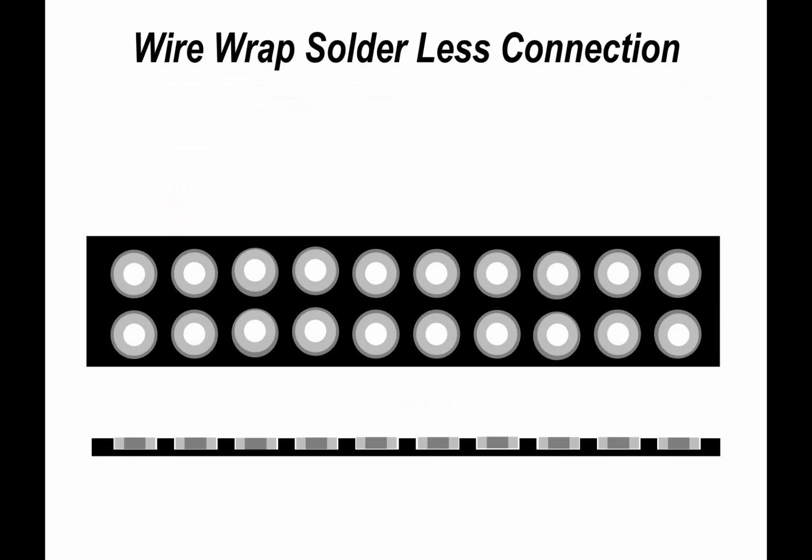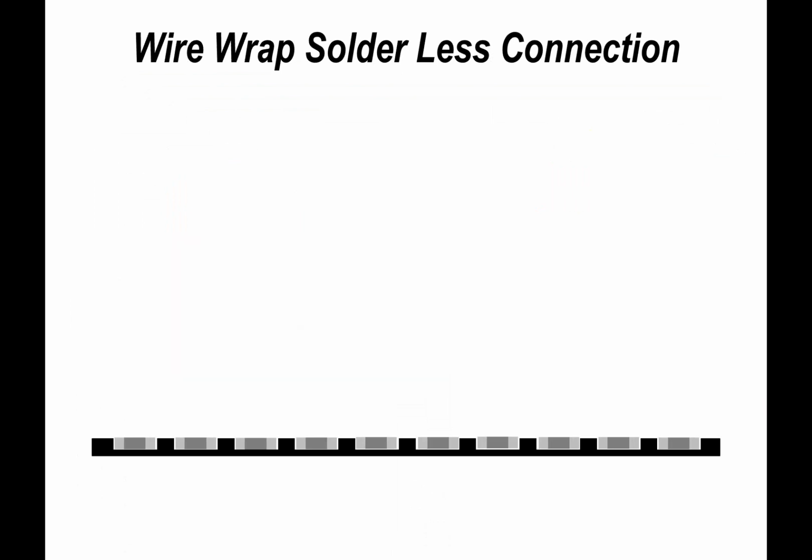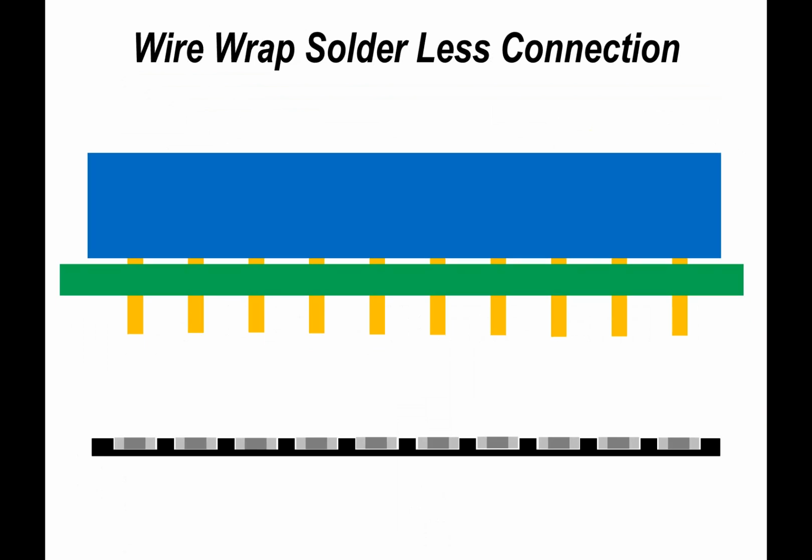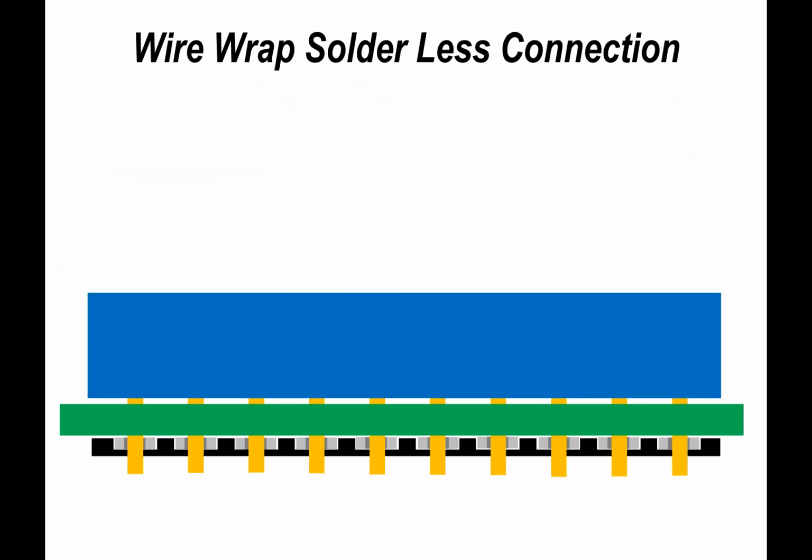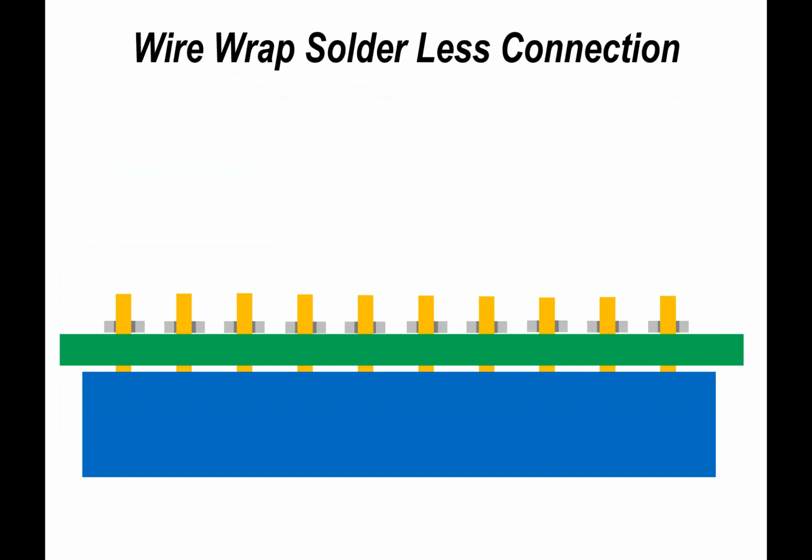Just imagine a pallet, like a solder pallet, with lots of little holes in. We would fill up those holes with preforms, and then lower the connector into the preform through the pallet, flip it upside down, and run this through vapor phase.